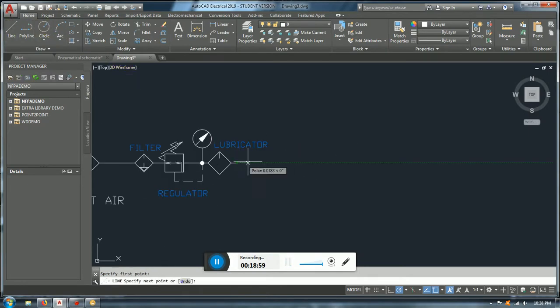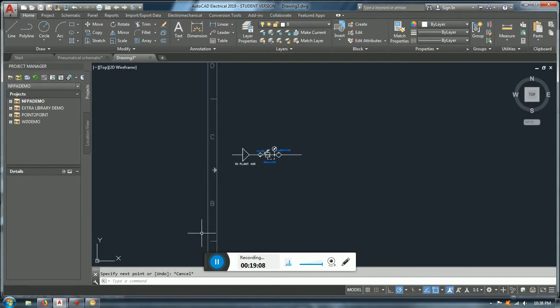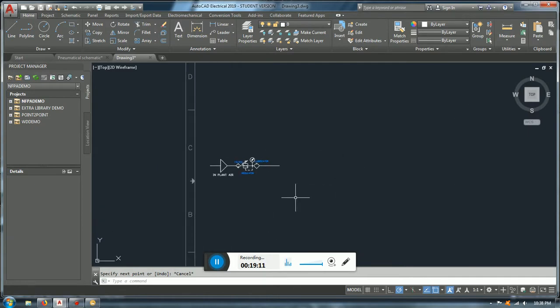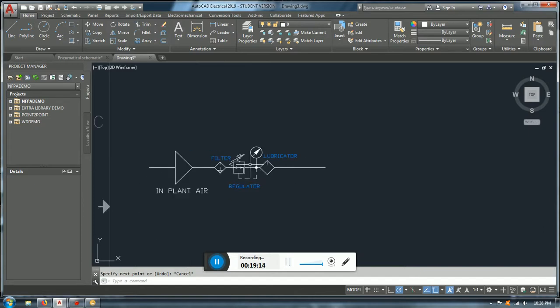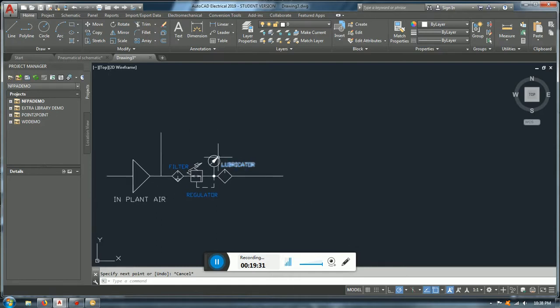Now, what comes next? I want to continue the pneumatic line, the air line, and here, pretty much, in our case, we don't really have anything else than a manifold with all the solenoid valves, okay? As I said, there is nothing really going on. If I want to do that extra line, I could do before or after. Doesn't matter really. In this case, you're going to do that before. If it's after, the pressure is going to be the one that you mark in the gauge. If it's before, it's going to be whatever pressure is coming, okay? Many times I see that before.